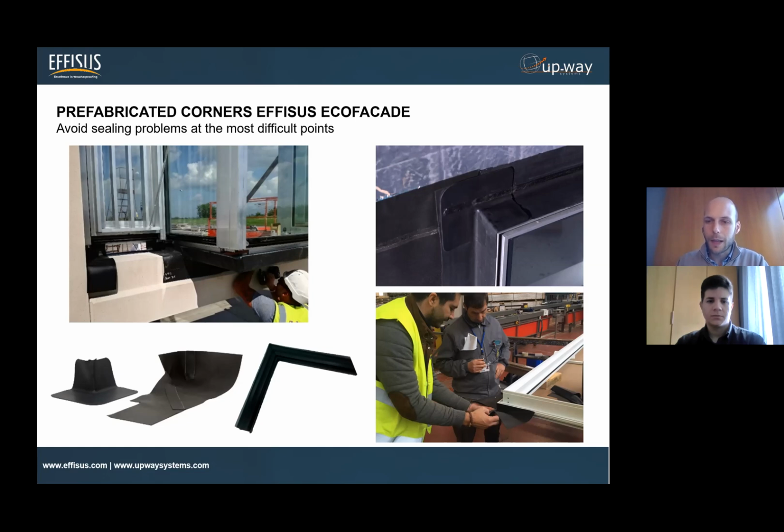So when we are relying this kind of interfaces on EPDM, that of course is a really durable material, already with many proofs in the construction industry of its efficiency and durability, here we are just opening a hole in our EPDM and covering it with glue. So this is the most simple one. Okay, that's why I like to mention here this case, because if we look into the most simple and understand, even there we have always a potential leakage point to understand the need of this kind of solution.